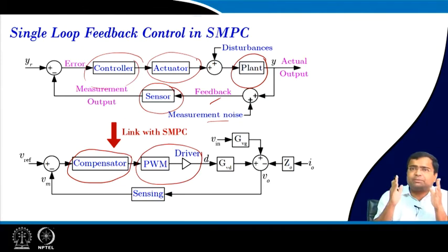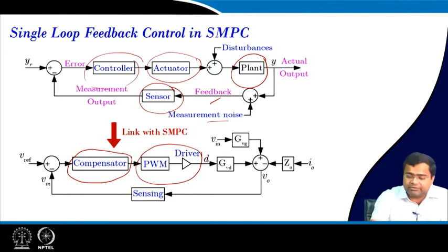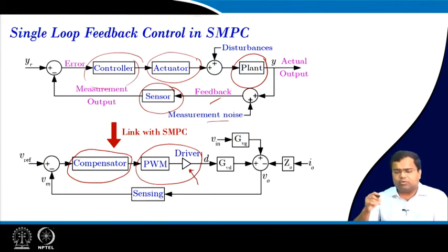signal. When you say PWM, that means we are generally assuming that switching frequency is constant, but it is not necessary. We can have also constant on time, off time, or hysteresis control, but ultimately you need a gate driver to generate the controllable gate signal for the MOSFET.